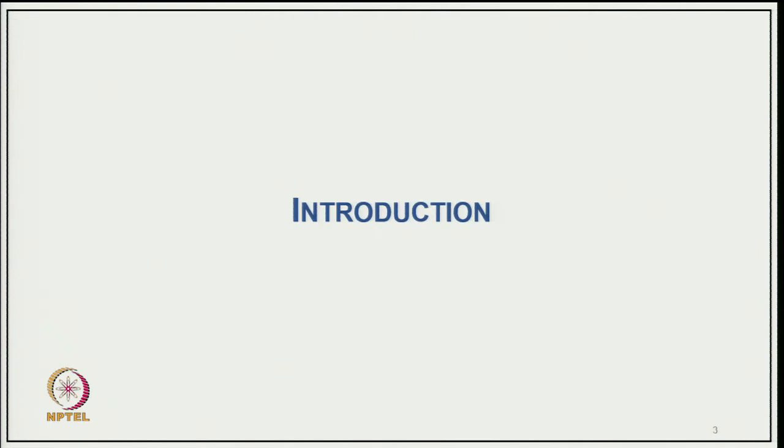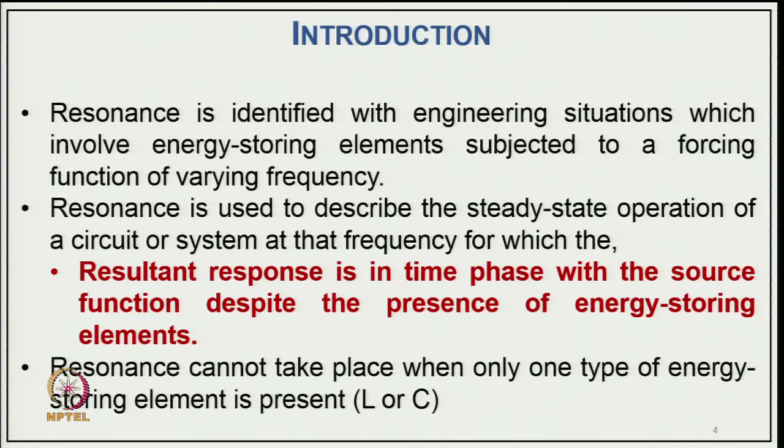Just to introduce it, resonance is identified with engineering situations which involve energy storing elements subject to a forcing function of varying frequency. Resonance is used to describe the steady state operation of a circuit or a system at that frequency for which the resultant response is in time phase with the source function, despite the presence of energy storage elements. Resonance cannot take place when only one energy storage element is present, either an inductor or a capacitor.